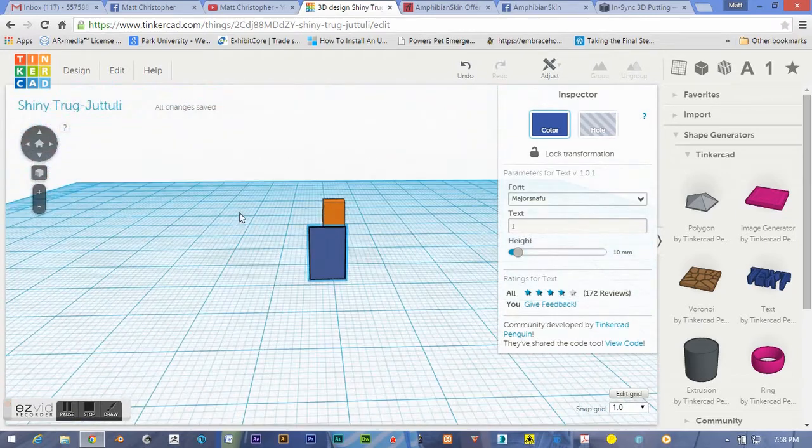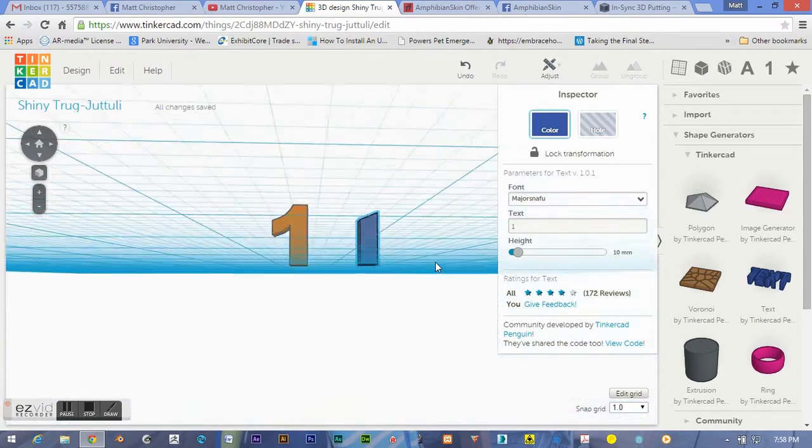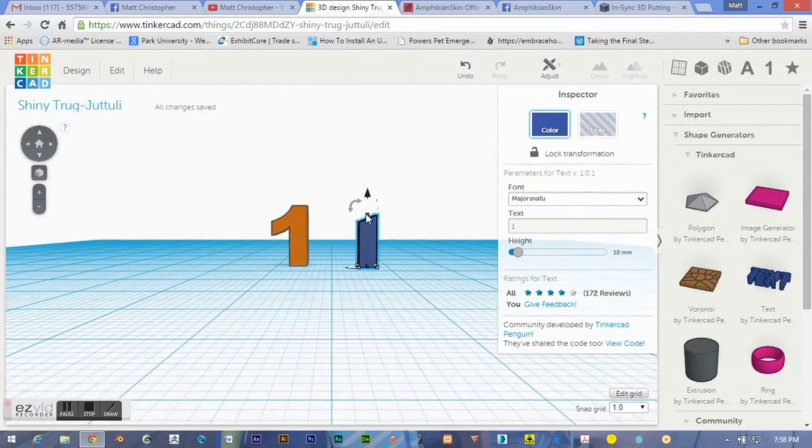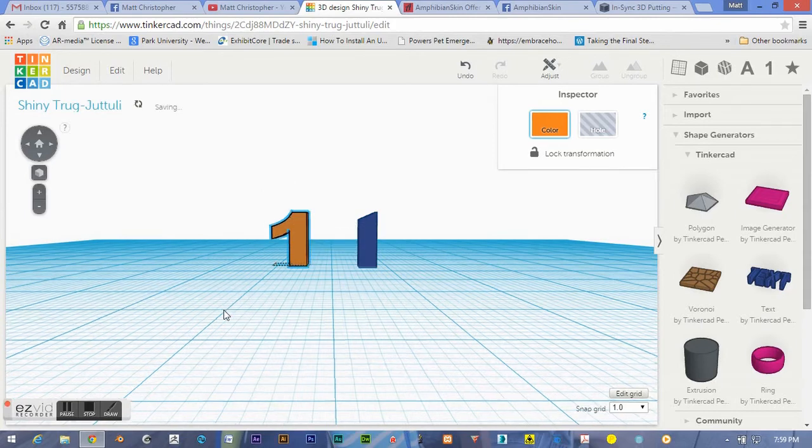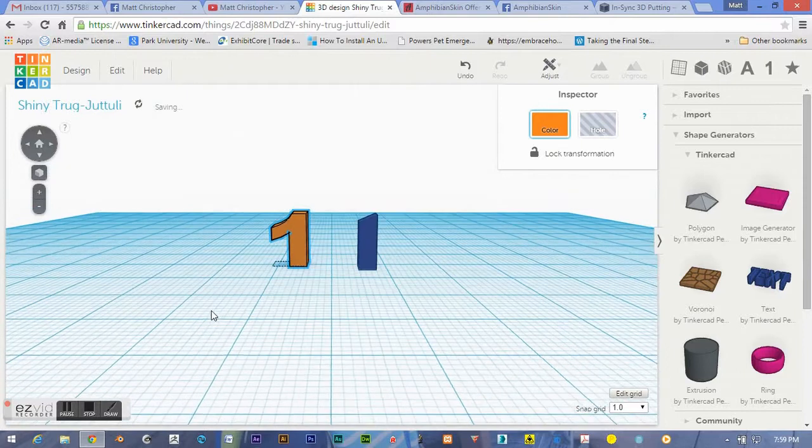We've gone through them all, and really this one does meet my needs. It has no overhang features. I can go ahead and thin it up there so it doesn't take the material, because really I don't need it to be very thick for what I'm going to do. So I can adjust the scale, set it to 10 millimeters, 1 centimeter tall.